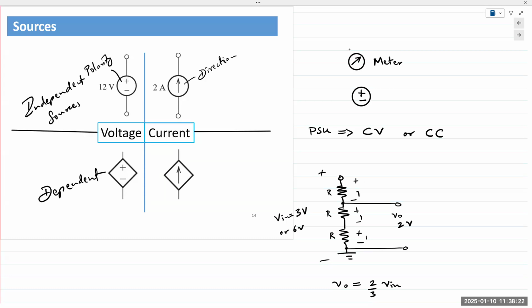This is just a practical example, but when we get to numerical models, as I said, for some of our models, especially transistors, we will actually use a model because the output of the transistor is dependent on some other part of the circuit. So, a 3-terminal device. There are multiple factors that go into that model, and it depends on some other part of the circuit. So for theoretical analysis, these dependent sources are very, very useful.